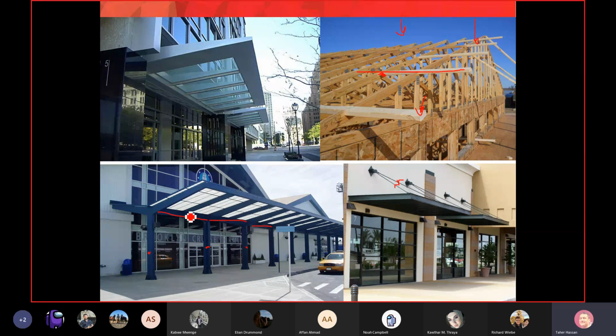You can see there is a beam which is framed outside from this beam. Please try to understand that when we have a gravity load like snow on top of this canopy, this beam wants to go down and it's connected to this beam, so it will cause torsion, because the moment is simply around the axis of the beam. That's why it will cause torsion.